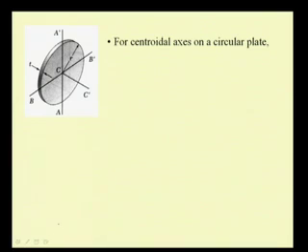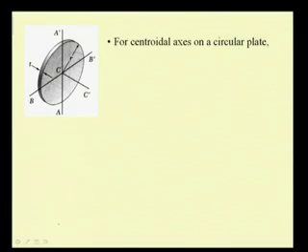Let us take another example. Here you see a circular plate. So, again we will see how we extend our findings for the second moment of the area in order to compute the second moment of mass for this thin circular disc. So, let us say we have a disc of radius r and thickness T, and we have this centroidal frame of reference A prime, C, B prime, C prime.